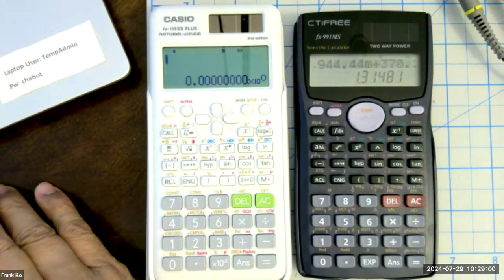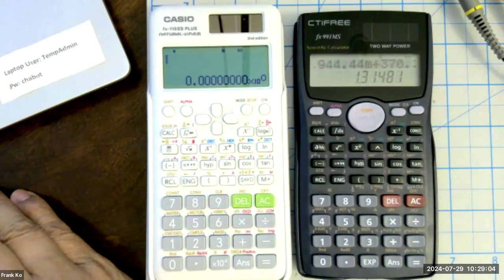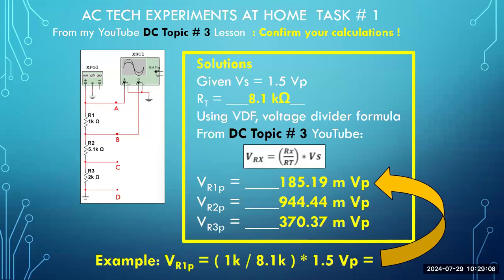so if we switch back out to the screen, go to share. So we add these two values of voltage, the 944.44, the 370.37, in order to calculate the voltage at point B with respect to ground. So our calculator just showed us 1.31 volts peak.